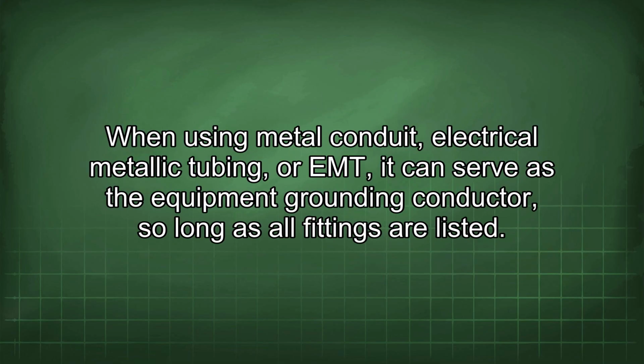When using metal conduit or electrical metallic tubing, or EMT, it can serve as the equipment grounding conductor, so long as all fittings are listed.